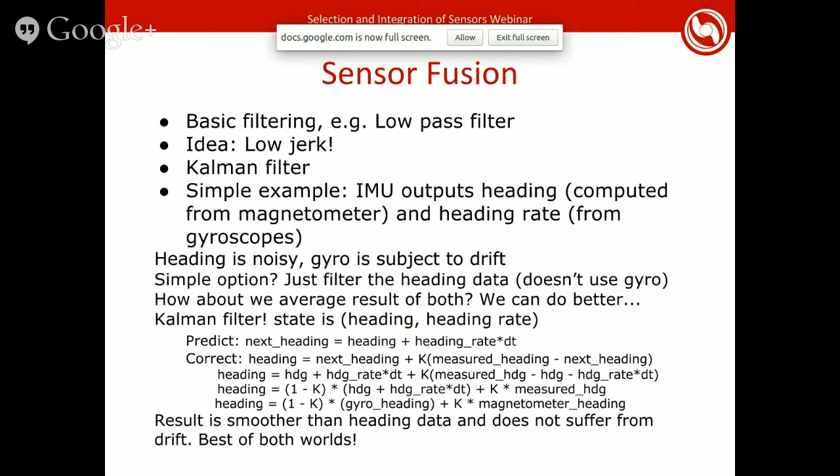So, for acceleration, usually any high frequency components of your acceleration signal are probably noise, so you filter those. That's a little bit of a higher acceleration, but not as high as the noise you see. I'm sure you've seen sensor readings that are just up and down, a lot of noise. That's a simple thing to do.